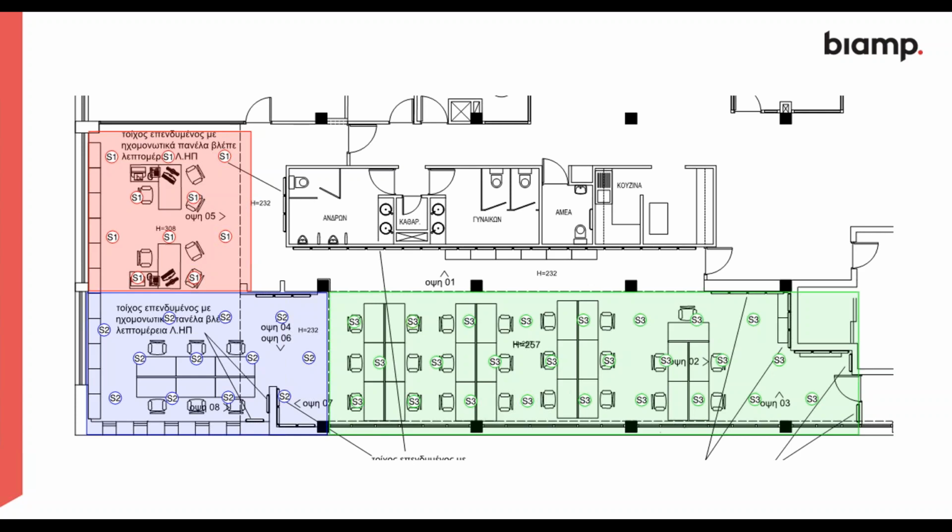Can the system be used for background music and masking at the same time? This is from Robert. Yes, it can. We would tend to have the masking on. Go back to the levels that we're talking about. The sound masking is maybe 45. The background music could well be higher, so we can use them at the same time.